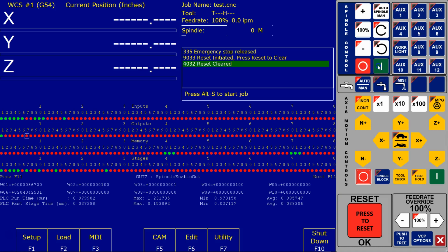Okay. This is very important because I've actually had a few calls where people had told me that certain things weren't turned on. And then when we team viewered in, what I found out was that, yeah, someone went in there and actually forced that particular output in the off state. So even though they were trying to do things in the PLC program to actually be able to turn it on, because it was a forced off state, it was never physically turning on.